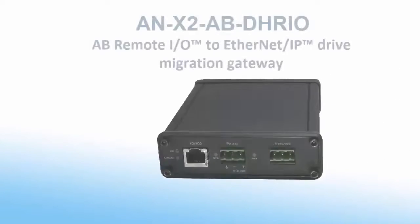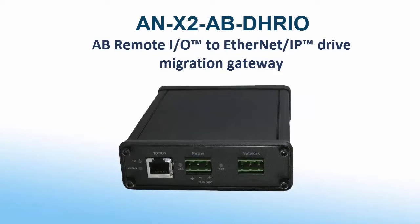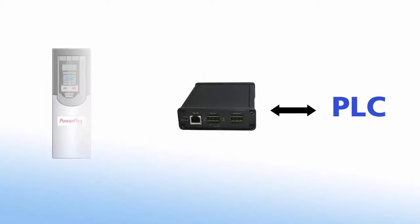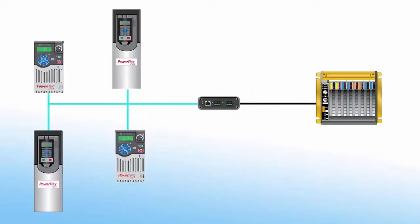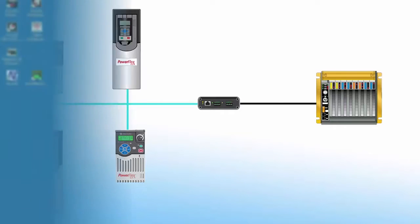In this edition, we'll be setting up the ANX2 Data Highway Remote I/O Drive Module to migrate a legacy PLC5 or SLC application with a Remote I/O drive to a new EtherNet/IP-based 753 PowerFlex drive without changing the PLC code. Each ANX2 module can communicate with up to 4 EtherNet/IP drives, allowing users to replace their obsolete 1305 or 1336 Remote I/O drives with new EtherNet/IP drives.